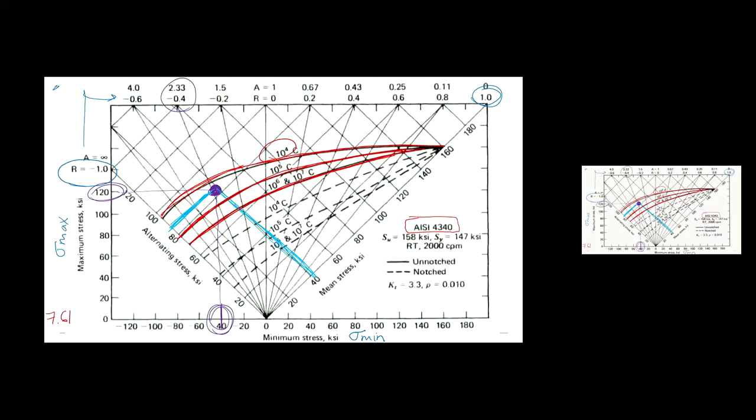So this is one way to compensate for non-zero mean stress. You find this master diagram and you go for it and you're good. Because once you get the alternating stress, it should match up with the SN curves for that material, right? So this is kind of like an expanded SN curve here, where you don't actually have to calculate and get back to it because it's already built in here. If you know the minimum stress, maximum, or just the other values, you can move around this chart to really work with a design problem.